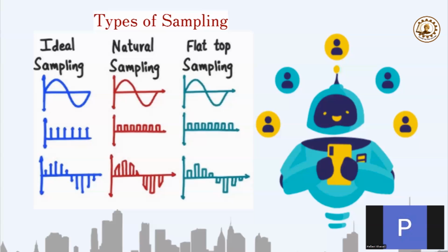So if your signal has frequencies of 50, 100, 200 hertz, the maximum frequency is 200 hertz. So you will take the samples at a rate of 400 samples per second, and only then you will be able to recover the signal when you are demodulating it. At the receiver, you will be able to recover the full signal, or convert those discrete time signals again into a continuous time signal, only if you have taken the samples at the Nyquist rate or greater, meaning greater than twice FM.